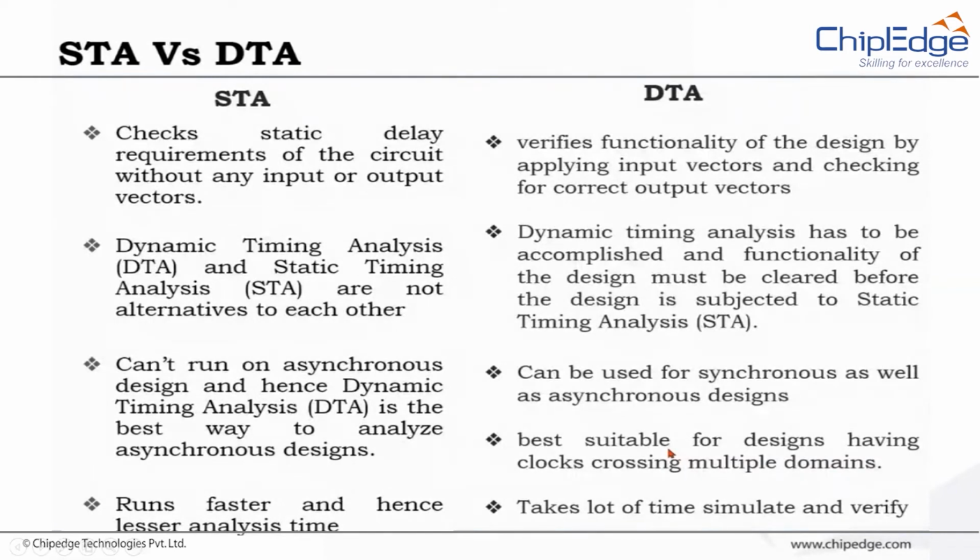So today's designs with very complex circuits and densities, running dynamic timing analysis simulations is pretty much limited or rare. But they have compensated it with other mechanisms, like CDC, clock domain crossing analysis, which takes care of your asynchronous versus synchronous domains and how signals are moving, whether it has been addressed or not.